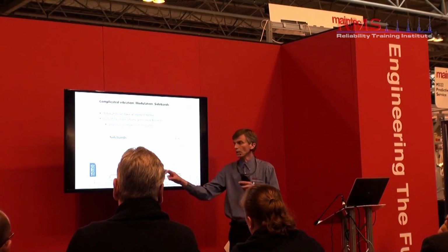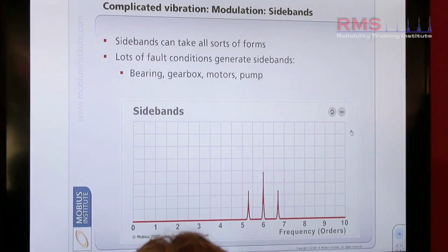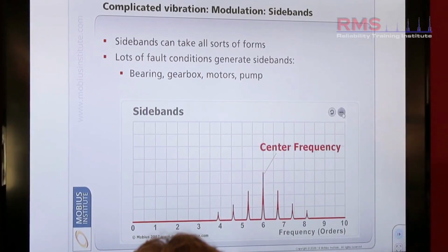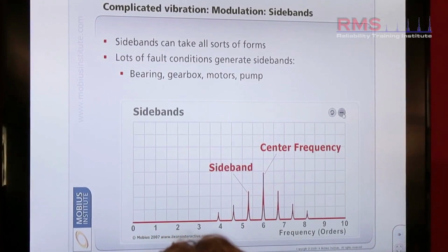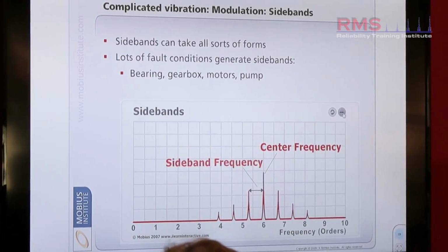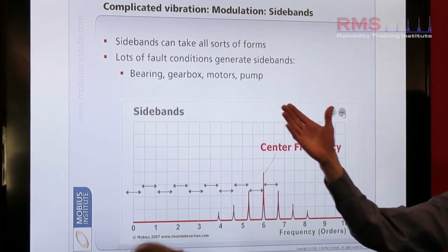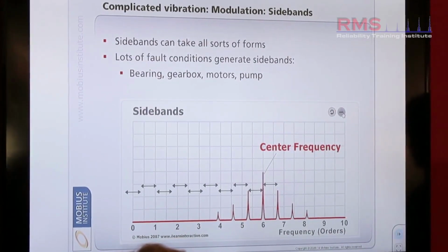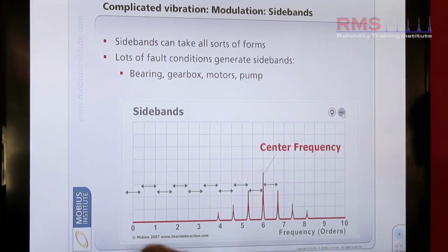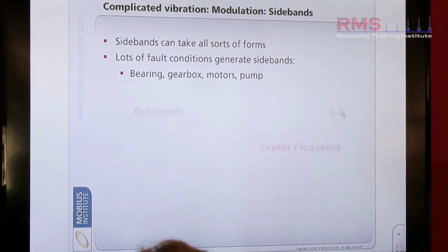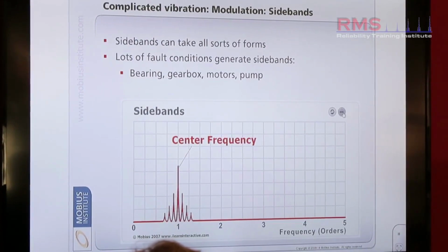These are equally spaced peaks either side of a central peak. So here we have several peaks equally spaced either side of the centre frequency. They are spaced by a delta, a difference in frequency that's known, and they're equally spaced. And they're common on bearing problems, gear problems, looseness, maybe electrical problems might be another one as well, where we see that distinct behaviour. And again, there are some more sidebands.